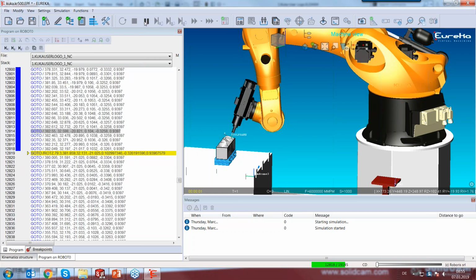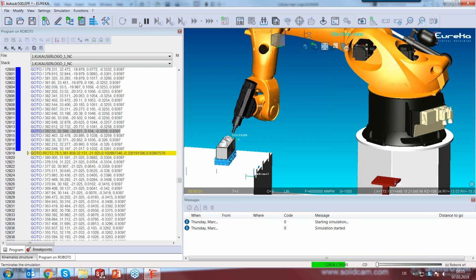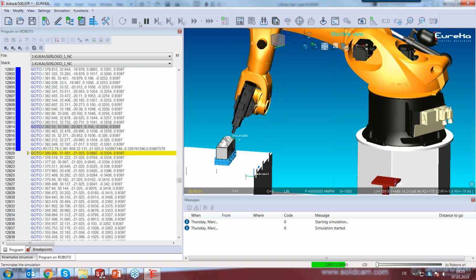And click the simulation. You see it's coming to the point, the robot rotates around the point and continues to work. You may think that this is not good, that the tool rotates on the point, rotates around the axis. There is a tolerance. Maybe you will get a gap or a gouging, that there are now different cutting forces and so on. We can solve this also in a different way.